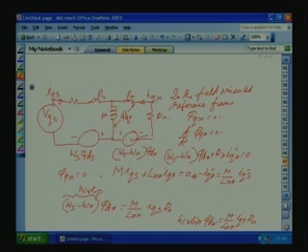Previously we have shown that under field oriented control, the torque is proportional to IQS. That means slip is proportional to the torque by keeping phi dr constant. Then by varying the orthogonal component, we can vary the slip, and in turn we can control the torque. So, we will continue this analysis, field oriented control, in the next class.